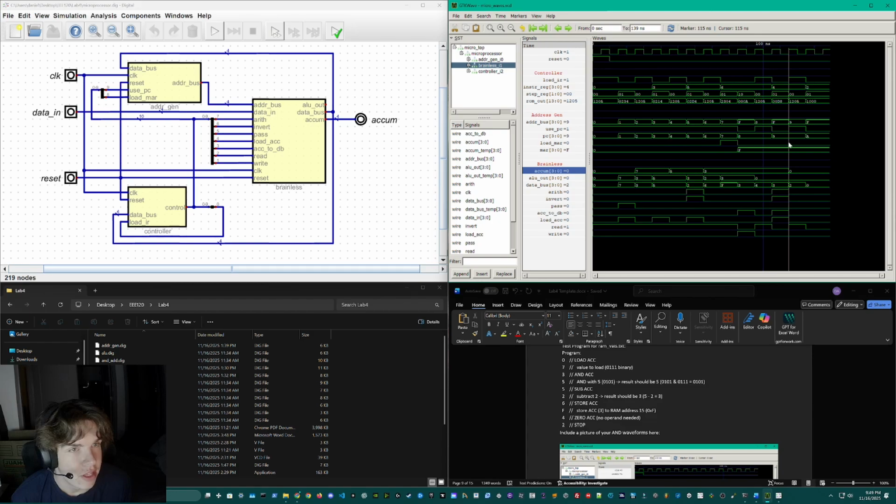Then we're going to fetch the 0 instruction, which is opcode 4, and 0 then clears the accumulator. So you see here the accumulator then becomes 0, and then we fetch the stop instruction. And clock 13, very final clock, we enter the stop loop where the processor finally halts with the done signal being high. And that is basically everything. That is all 4 instructions working properly.